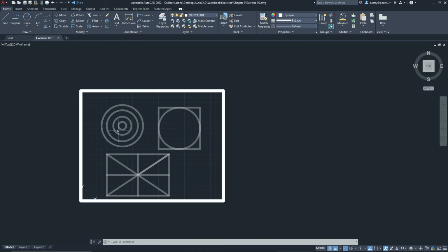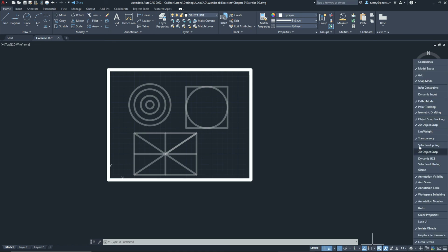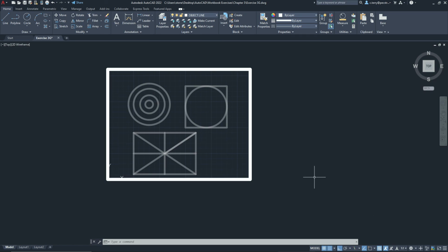Select the transparency status button to show or hide transparency. Let's see, where's that at? Okay, sorry about the weird cut. I had to do some other investigating. It's right here on my bar at the bottom. There's one that's called transparency. Mine was just unchecked, but basically what it's saying is with that there, I can either change it on or off for whenever you're drafting and drawing. So mine's turned on right now. That's all it is. It's always something with AutoCAD that's just a little simple thing that you overlook or mistake.